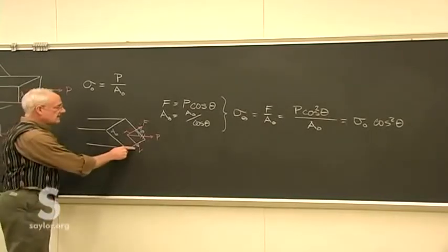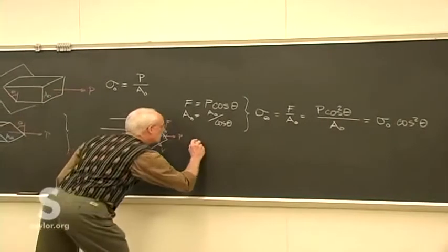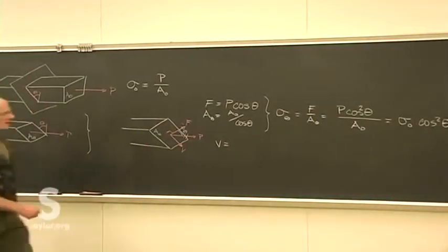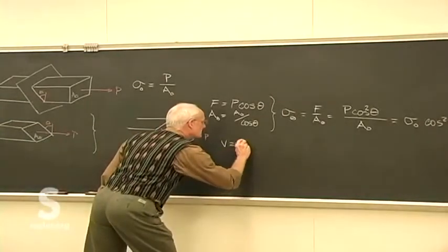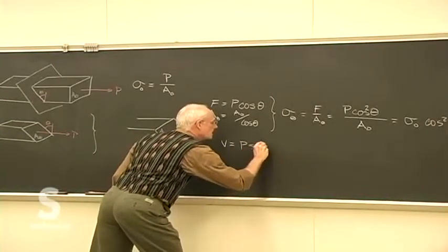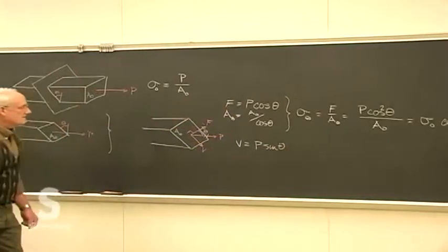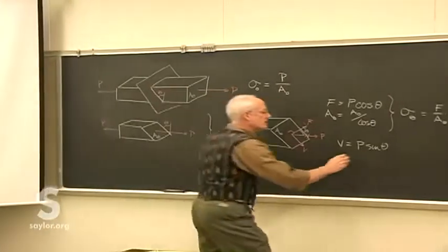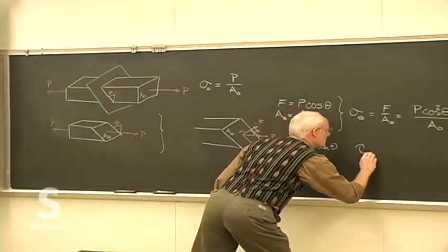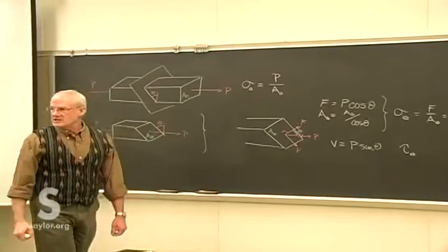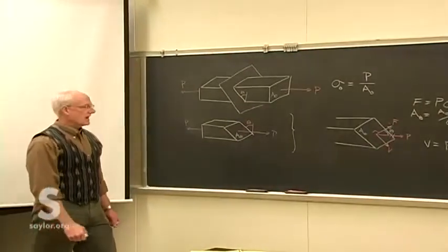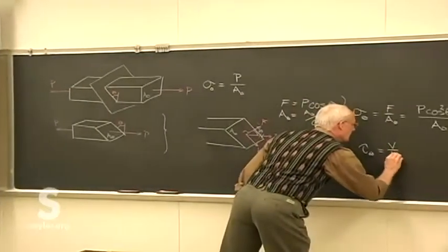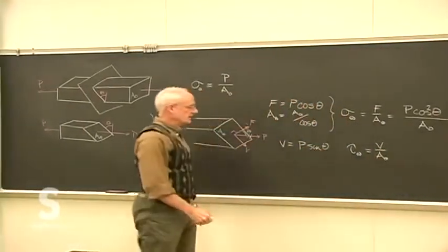Let's see if that same kind of thing holds true for the shear stress. So the shear stress, let's see, that's the load times sine theta. So the shear stress, the average shear stress at some imaginary plane at some arbitrary angle theta, is V over the area over which it acts, which is V over A theta.